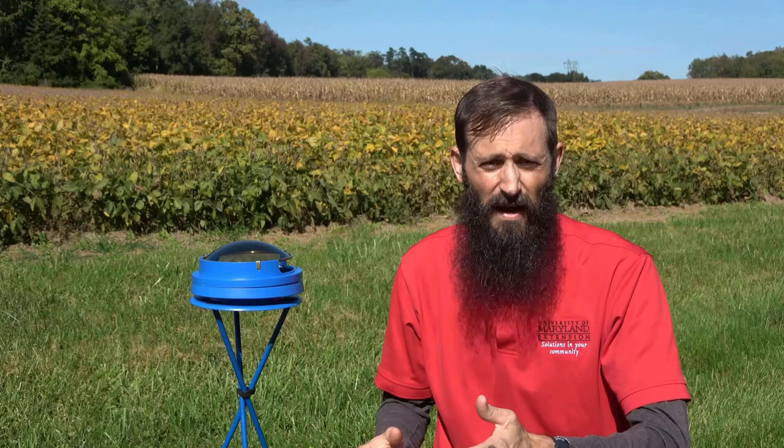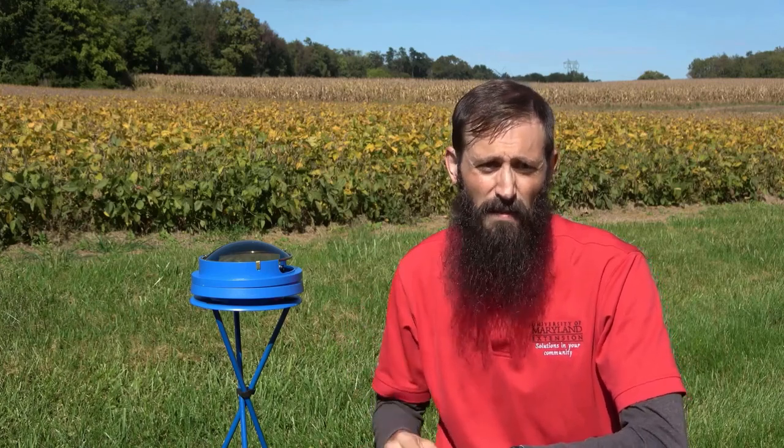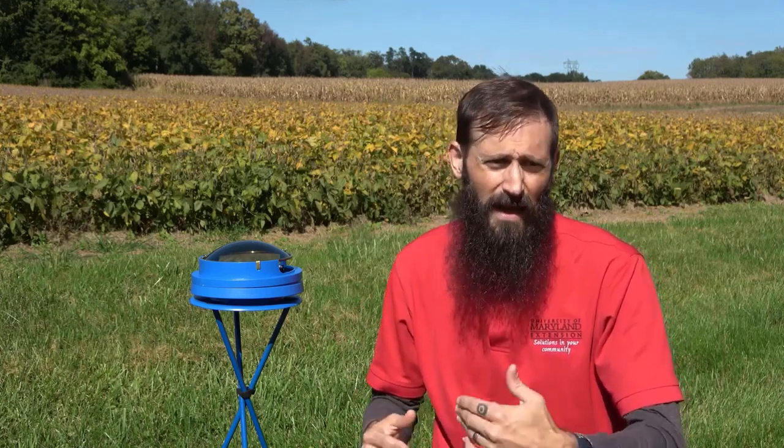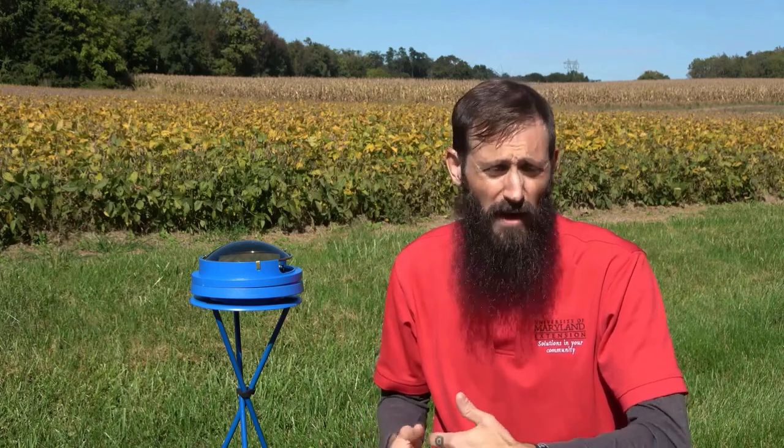But how would you assess the shading from a tree like this at a different time of day or a different time of year? While we could spend a whole year taking notes on where the shadows are falling on this site, we're going to consider a more practical approach to assessing potential installation locations here at this site. Site assessments can be performed using various tools, including a magnetic compass and a sun path chart, but it may be more practical to use a professional site evaluation tool like this Solar Pathfinder, especially if you anticipate an assessment of multiple sites or locations.